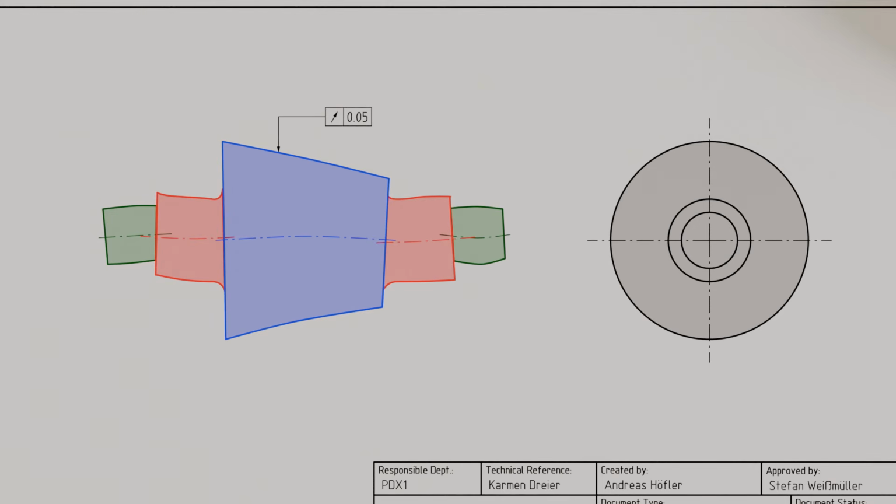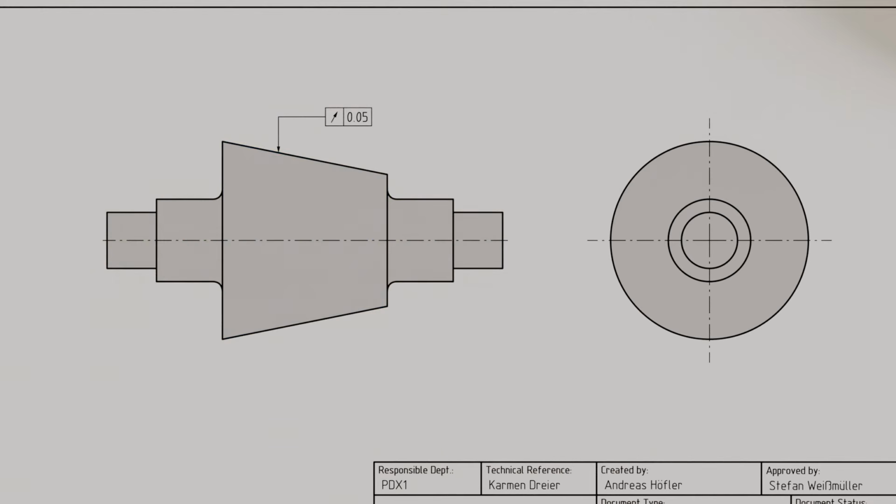Accordingly, it also makes a difference whether we align the shaft for rotation on the bearing surfaces marked in red or on those marked in green. Depending on this, we obtain a different datum axis for the rotation, and the dial indicator readings will produce different results. Therefore, a datum must again be specified to clearly define the alignment of the part for rotation and the resulting runout. In the present case, we choose the larger shaft shoulders, more precisely the centerlines derived from them, as the common reference. The part must then be aligned or clamped on these shaft shoulders during the runout inspection.